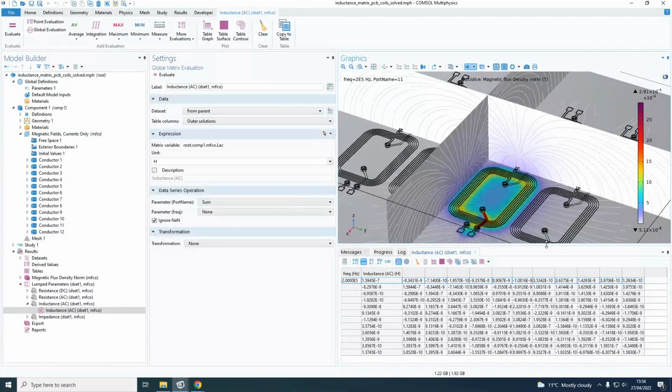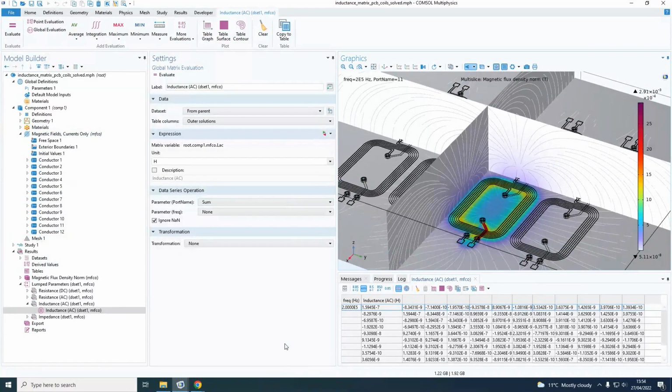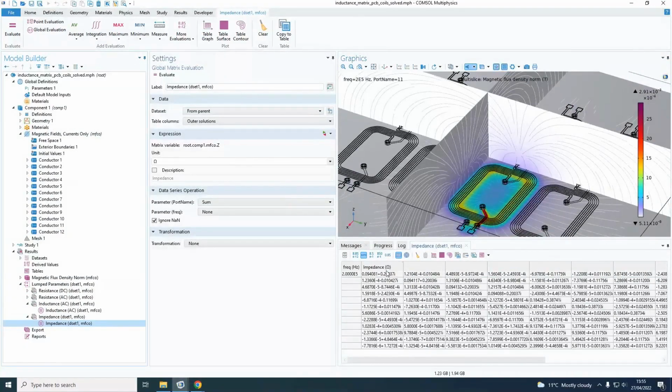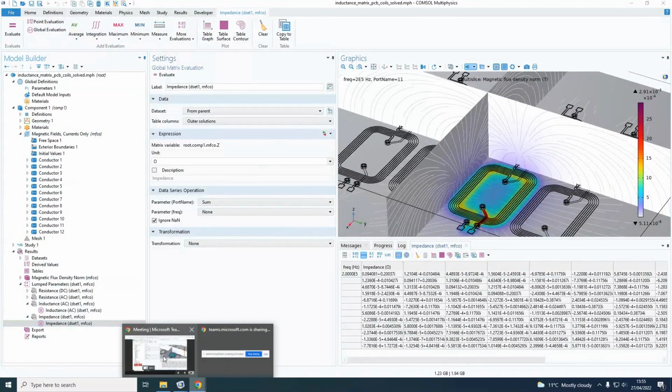So it's possible to get other numerical outputs from these things as well. I mean, you can see already it's given us by default the impedances. So these are the impedances as seen on the coil inputs for these different coils, real and imaginary parts, at the frequency that we used. You can get other lumped parameters as well, such as the voltage that you would need to apply to drive this much current through the coil and that sort of thing. So hopefully that gives you a taster of how these models work. If we can go back to the slides now, please.